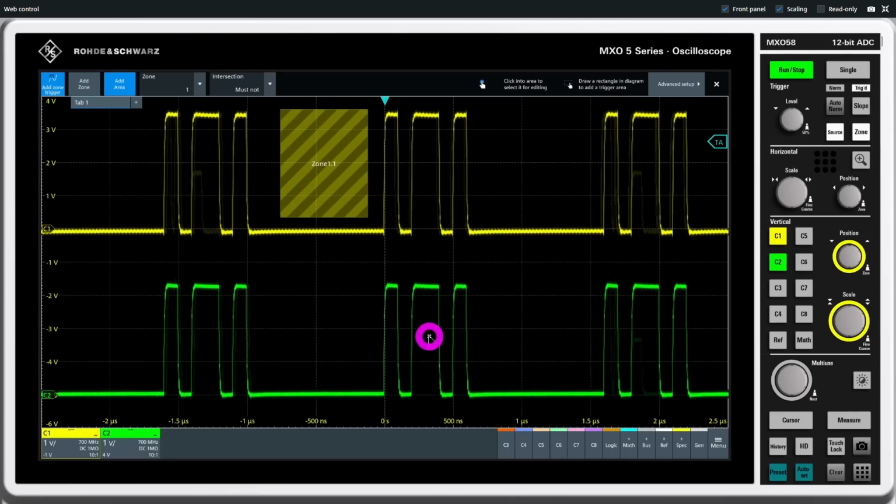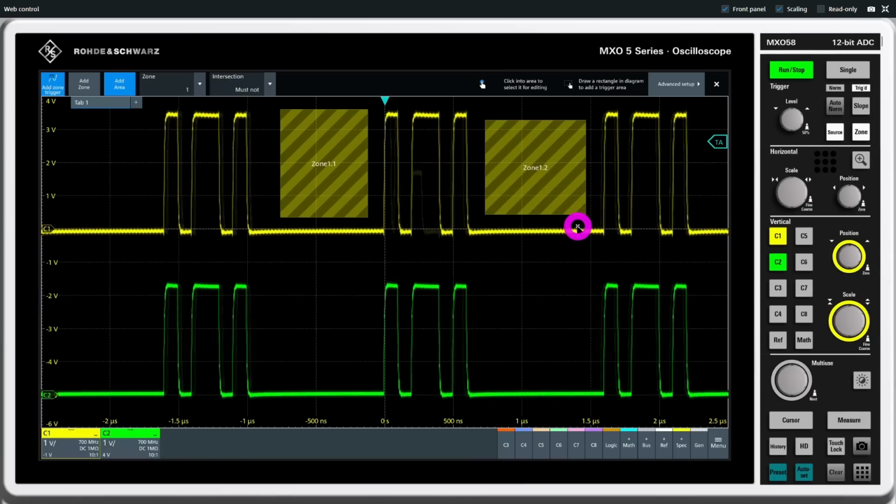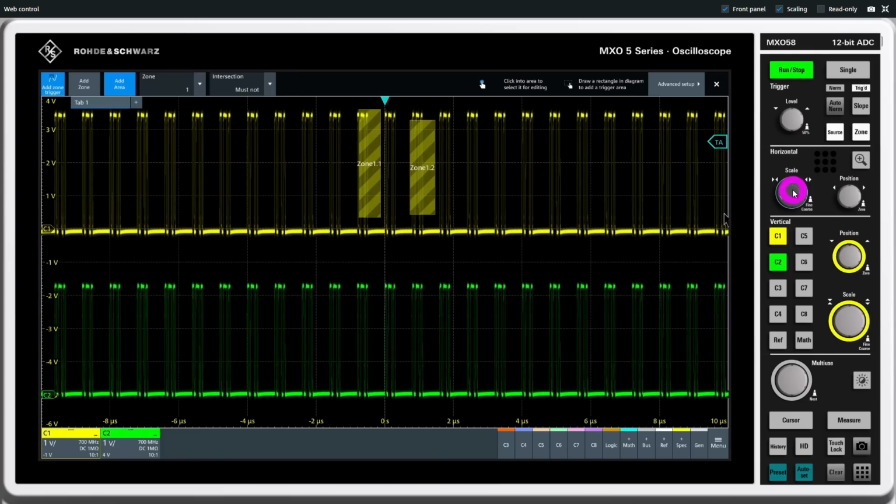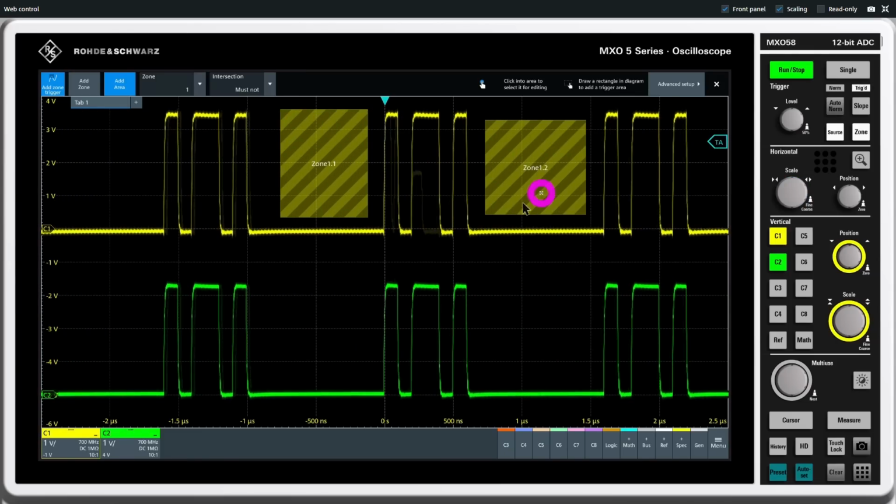And look at that. Now the waveform that is being shown is only on these rising edges. All the other ones are being abandoned. I can also draw one over here, really trapping the waveform between these two exclusion regions. And now I can scale everything too if I want, and everything scales with it, and everything is completely stable. It is just so much fun to play with this.